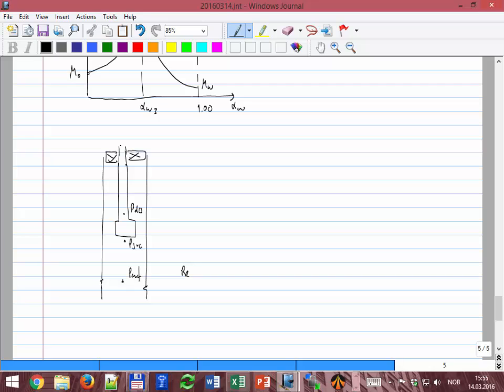So how do I do that? I go and calculate the available pressure at the suction of the pump. I have the rate, the Q, let's say, of oil. With the Q of oil, the reservoir pressure, and the IPR, I can calculate the flowing bottom hole pressure. Then I can move all the way to the suction. I have P1 and I want to calculate P2, right, in our equation, and I can calculate the P of the suction of the pump. Then I stop.